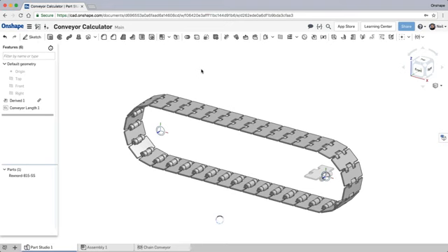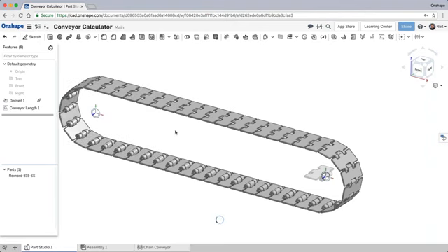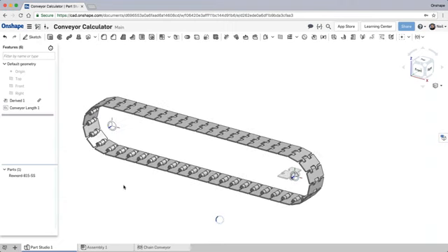So when you actually come to create an assembly, you can see these things called make connectors, which allow me to position the sprockets. It just means that it's very easy to define something from the very beginning. And because these behave just like regular Onshape features, you can make a design change at any time. So if, for example, currently I've set this to 700 millimeters as the width of the length of the conveyor, if for some reason I need to make a design change, it is simply a feature in the list which I can go ahead and edit.